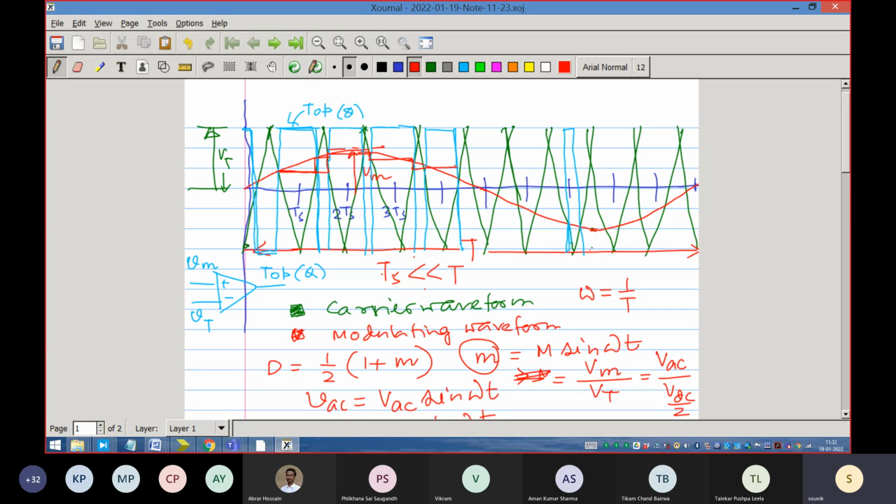In low frequency we are going minutely, angle-wise minutely, at a very high resolution. But when you are generating a sine wave of higher frequency, we accordingly skip a few samples and then produce it. So the quality of the sinusoidal signal varies. In low frequency, we need a higher resolution. Practically also, we need a higher resolution compared to the high frequency.